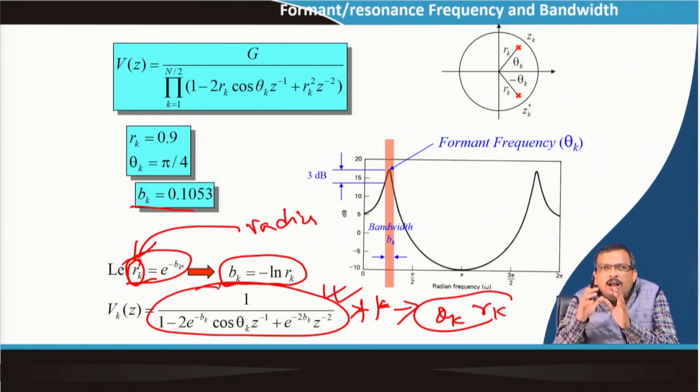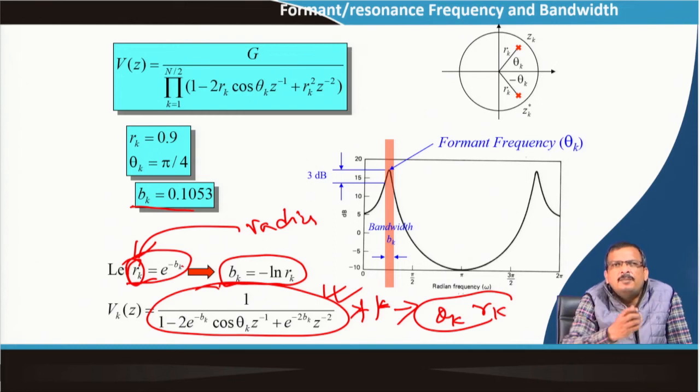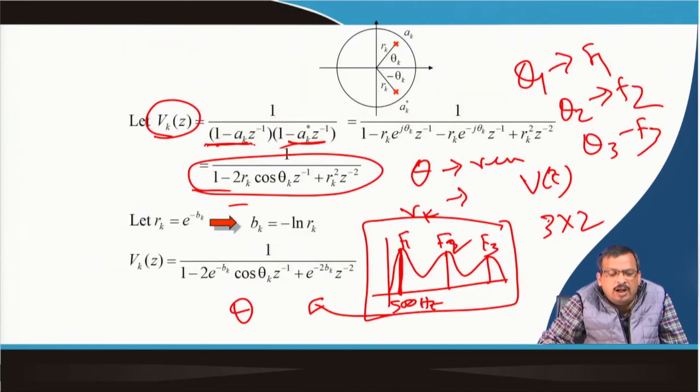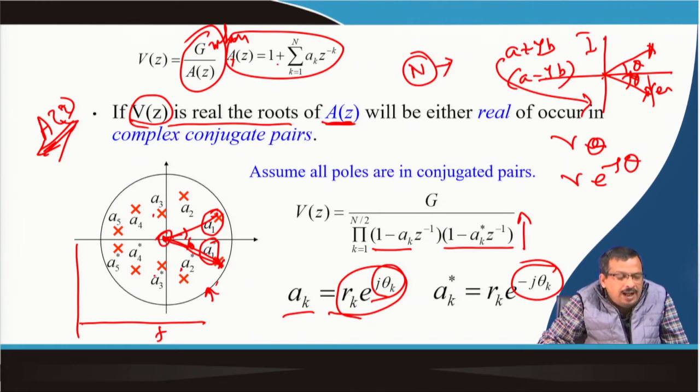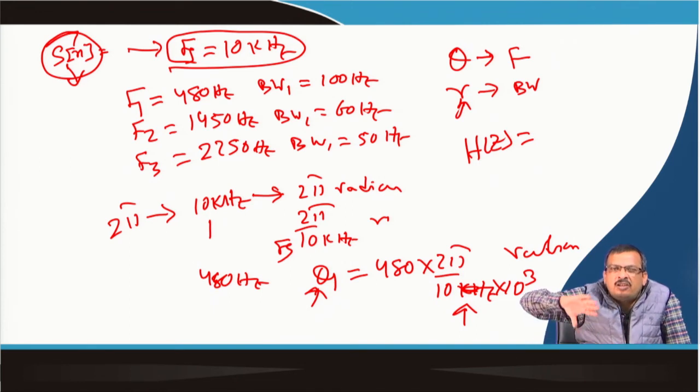So, the Z domain representation can give me the frequency response of the system by analyzing poles and zeros. That is why the pole-zero concept is required. As I discussed on stability in the first class on Z transform, if the poles are on the unit circle, it will be a self oscillatory system.